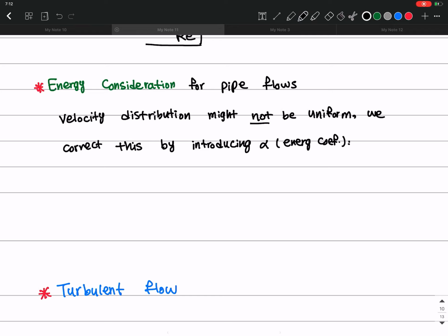So in the energy equation, which was a more comprehensive form of the Bernoulli equation, we derived it using energy principles, right? For internal energy, kinetic energy, and potential energy, if you remember. And it was a generalization of the Bernoulli equation by accounting for friction in fluids.